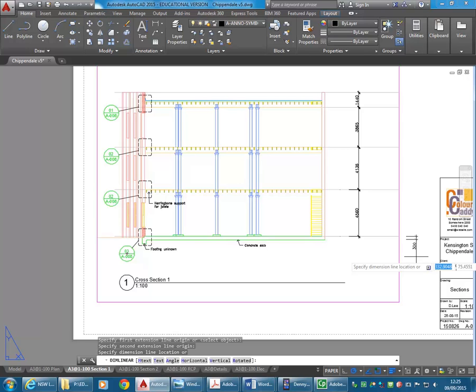So it's not like drawing dimensions on the page. If I did the same thing over here, notice how the measurement isn't 300, it's 6 mil or whatever the distance is on the page. But because when I did the dimension I snapped to things that are inside a viewport, even though I'm not in model, it will pick up that measurement. Which is pretty clever, I think. So you do have the option, if you've been wondering, of dimensioning on the page. And some people only do it like that.